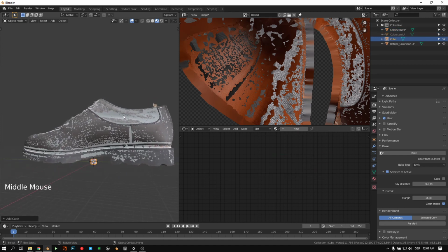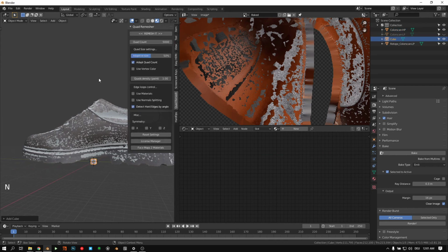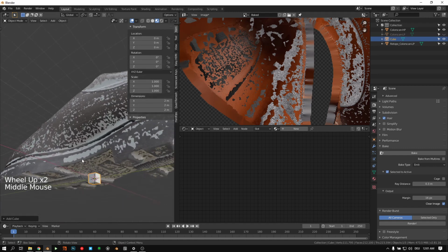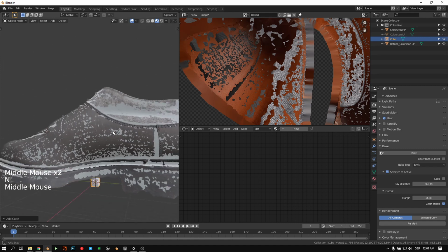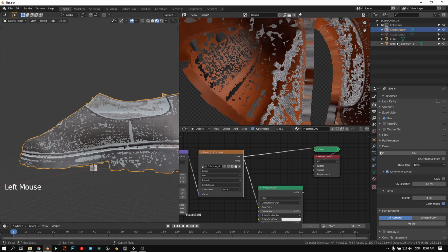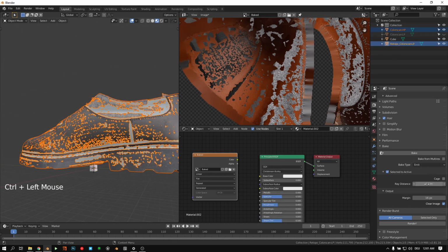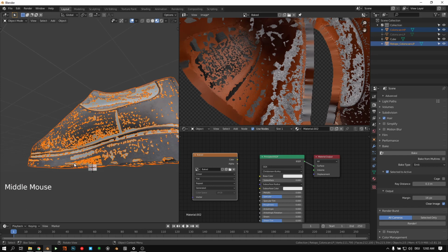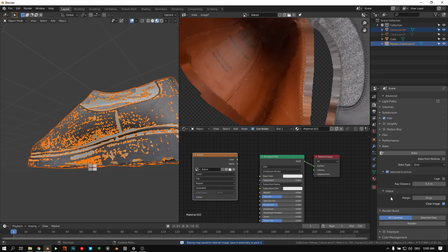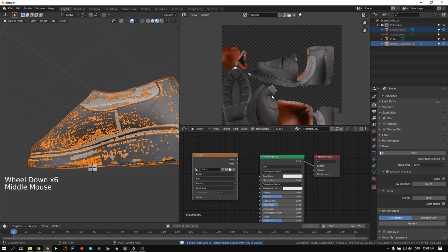And if you go to your properties sidebar by hitting N, go to item, and here dimensions 2 by 2 by 2 meters. So this is 2 by 2 by 2 meters. So now you have a frame of reference. Now same procedures, first select the high poly, then your low poly, and now you can bake, and now you could see, okay, 0.3 maybe makes sense. Let's try this. Okay, this is looking way better.